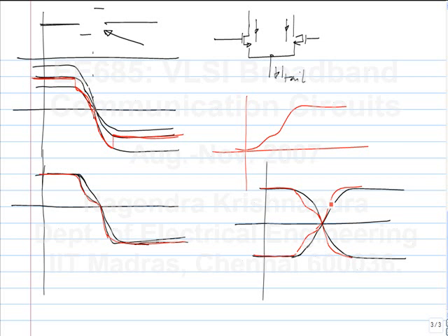If you look at the differential waveform, they do sum up to 0, because you get the positive one in one case and the negative one in the other case. So it does sum to 0. But if you look at each of the single-ended waveforms, that will be non-linear. That will look different for the rising case and the falling case.